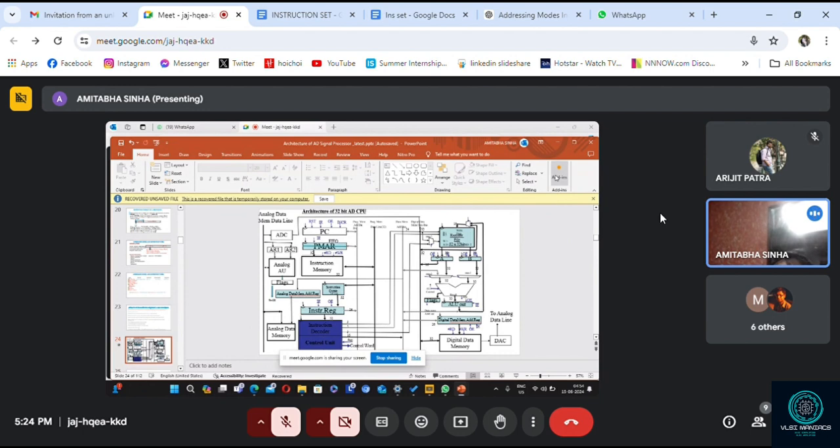Now, what is the inductor? The inductor is based on Faraday's law of electromagnetic induction. E equal to L di by dt. The induced voltage is equal to L into the rate of change of current, which comes from the rate of change of flux. So the inductor has a differentiator property; it is doing the differentiation. A resistor has the linear property, V equal to I into R.